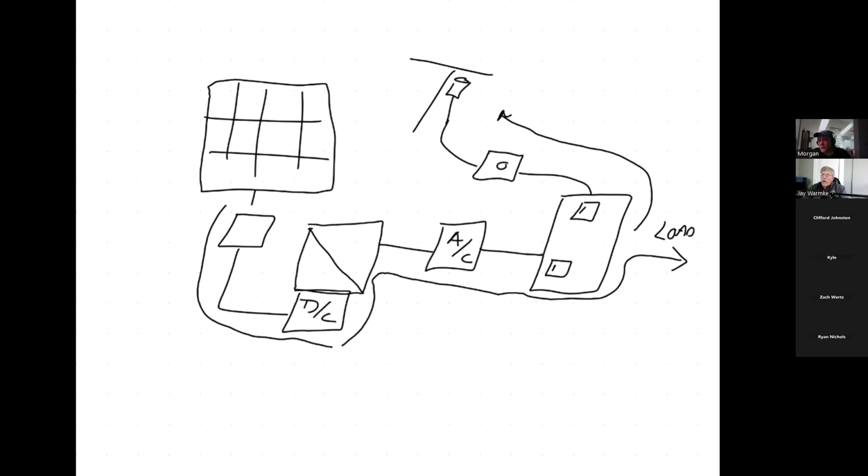They also don't know what loads are connected to the grid, because if my solar array is generating power and my loads are being serviced by that power, AEP doesn't know how much I'm generating and how much I'm using. All they know is what's flowing through the meter. That's all they know. So there's a significant amount of power that's hidden from them.